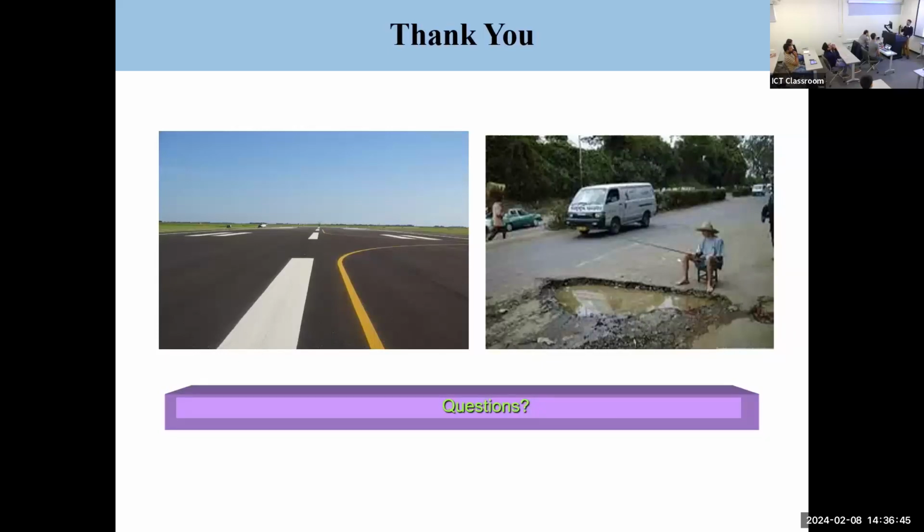Okay, I'm going to answer your question in two parts. One is the yield surface. What I love about viscoplasticity is that you really don't need to stay on the yield surface all the time. One of the difficulties in computational plasticity is that whenever you get out of the yield surface, you need to return your stress level back to the yield surface, and that is difficult.